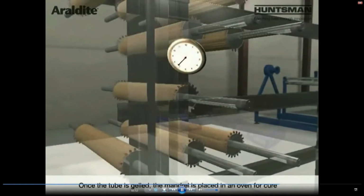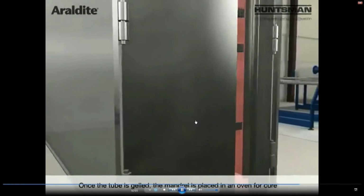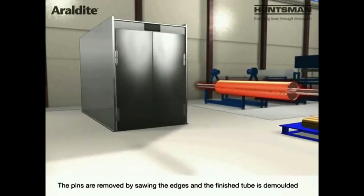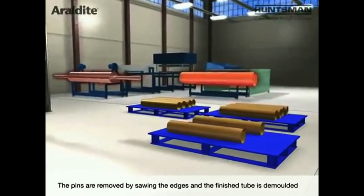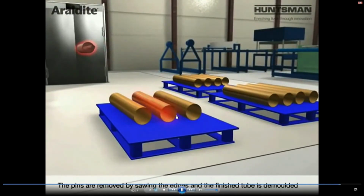So this is the oven. These are the mandrels with the wound composites. Once the time is over, it is taken out. Once the tube is gelled, the mandrel is placed in an oven for cure. When the curing process is over, the pins are removed by sawing the edges and the finished tube is demolded. We can see here the mandrel has been removed and this is the final product that has been produced.